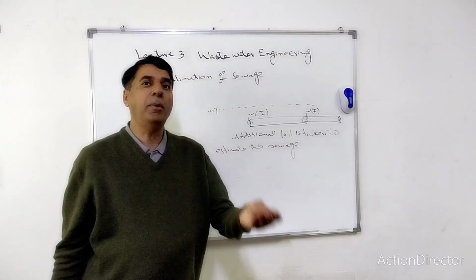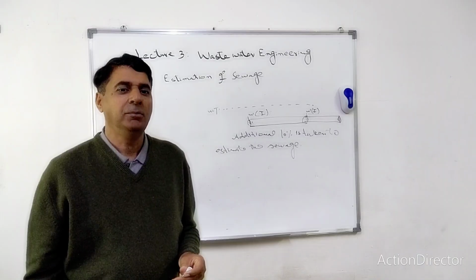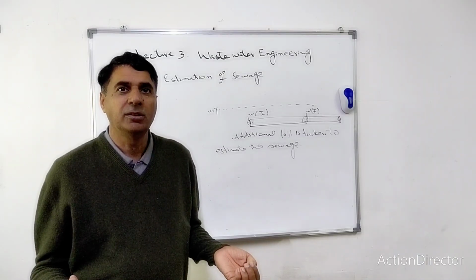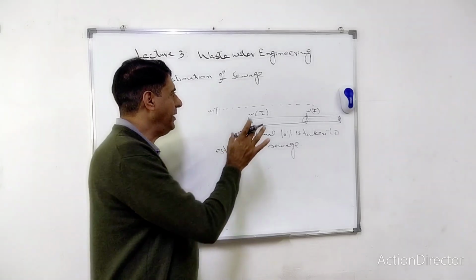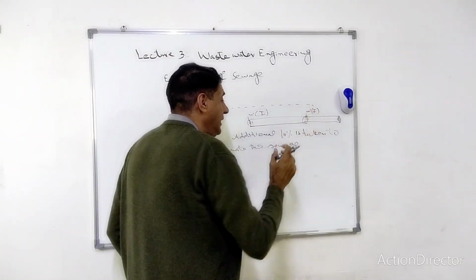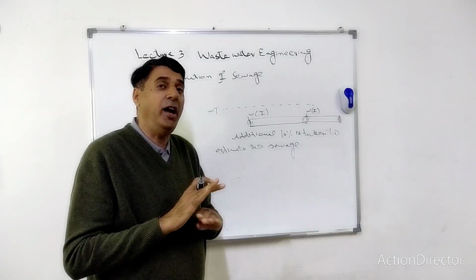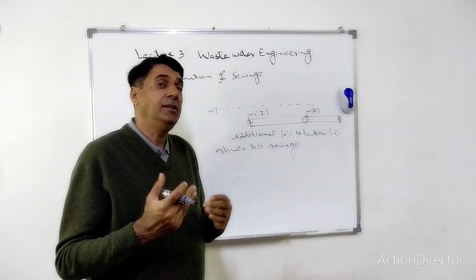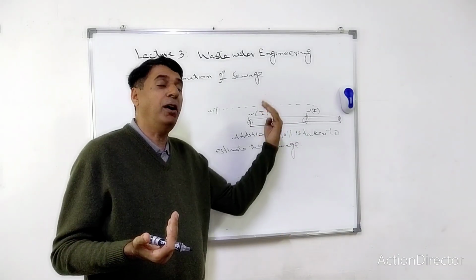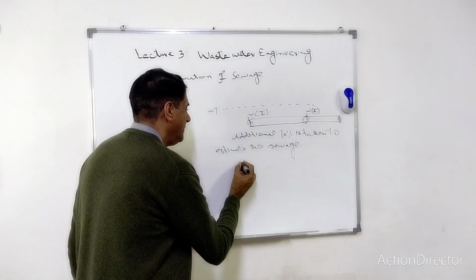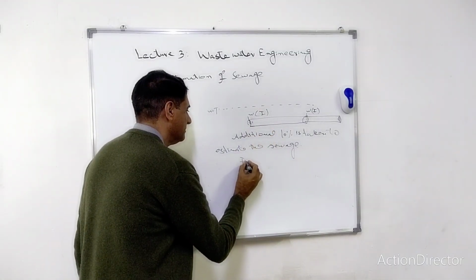But in my situation, because I am working on the sewage project, I assume that all these pipes are very tight, and there is no chance of damage. No water can penetrate through the joints in the pipe. So in this way, this inflow is taken as zero.